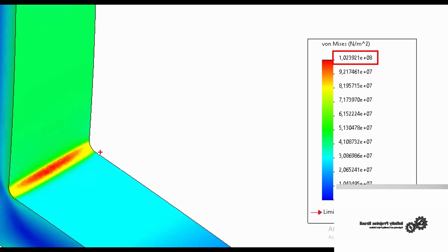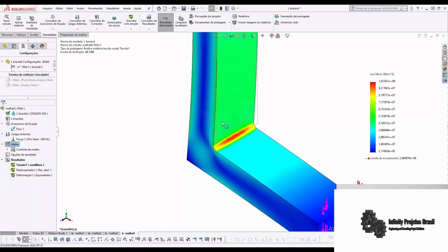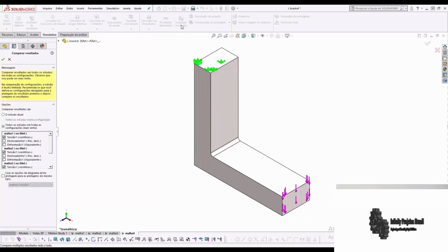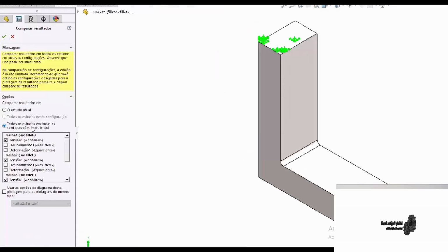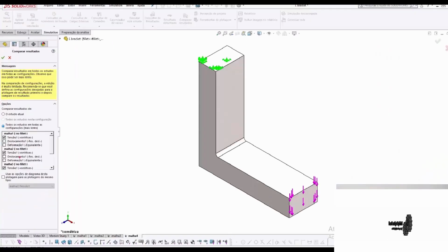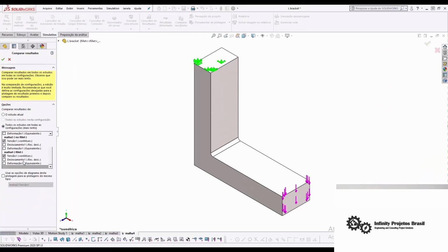I'm going to leave the comparison table here. Beyond stress and deformation, which allow us to have an idea of what will happen to our model internally in its structure, we have other types of results to analyze what happens externally, such as a reaction force plot. For this we go to results and define a post to list resultant forces.